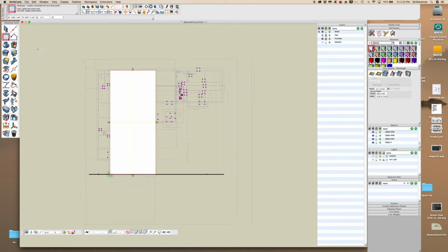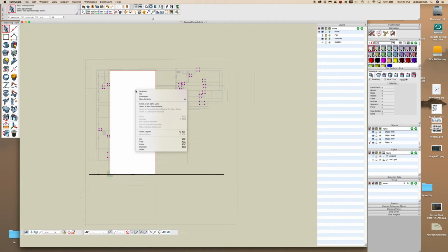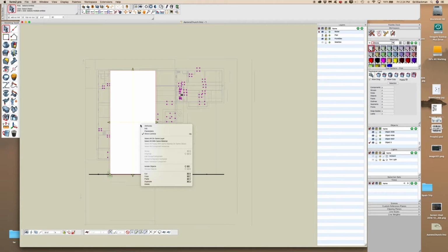Okay. So when I go back up here and select the selection tool and click off, it disappears. If I hold the Command or the Control key down, I've got to make sure, when looking over here, that it's solid. I want to pick the object. I hold the Command key down and click on it. I get this dialog box. If you can see this, it says Show Controls. I have an opportunity at any point in the modeling process to move it around. So you can go back in here and modify this by showing controls, and those controls will stay there until you click on it again with the Control key down and deselect Show Controls.